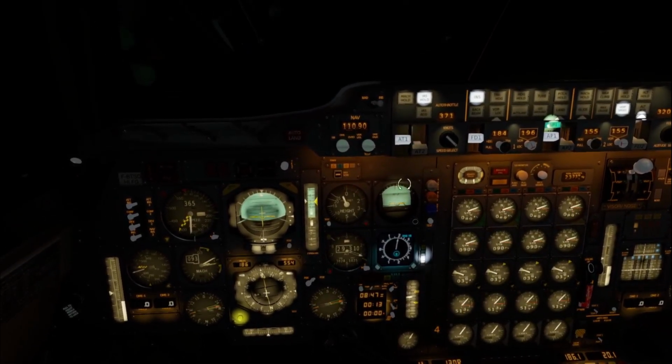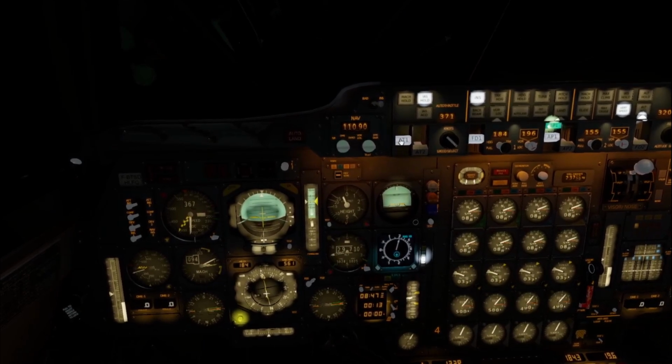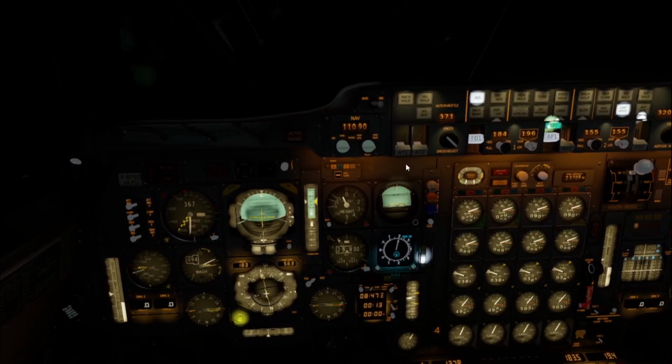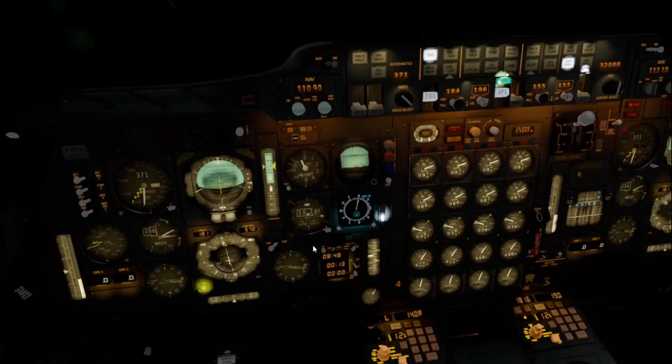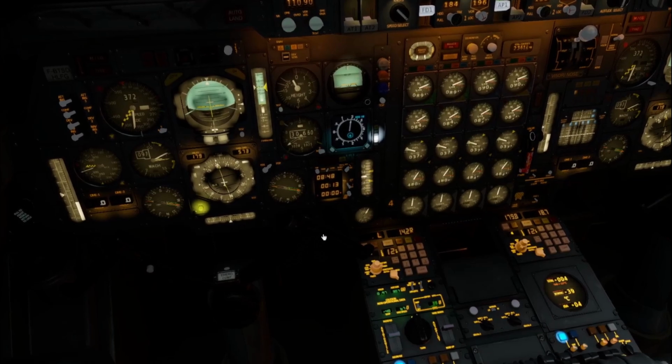I'll set on 500 feet warning for the Sydney, and watch the speed even below Mach 1. The auto throttle may be faster, so we'll stay at 30,000 feet. We will stay at Mach 0.95. It's getting faster, so I'll slow down a bit. Always watch this instrument or this one for the speed. So now it's, let's say, steady.